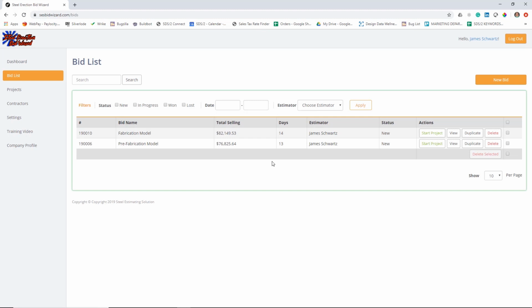So that concludes today's first webinar about the bid phase. I was able to cover the power of using the fabrication and the prefabrication model and able to get quick and accurate bids out. I was able to utilize SDS2's crane placement tools to determine where I wanted my crane placements to be for the least amount of lifts. Make sure to tune in next week where I'm going to break down the erector sequences, utilize more tools for the crane layouts for the erection views, and also sending all of this information to Fortisee for load planning.